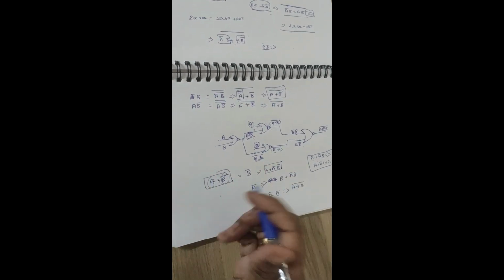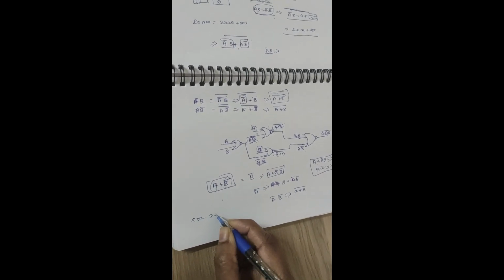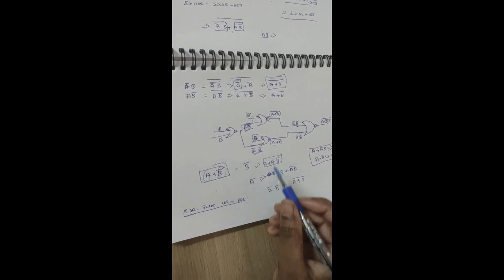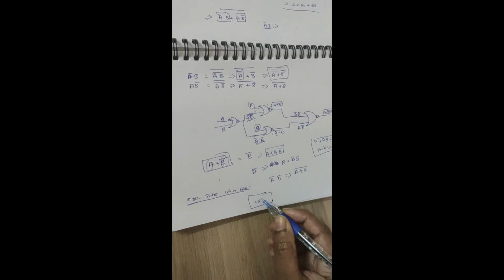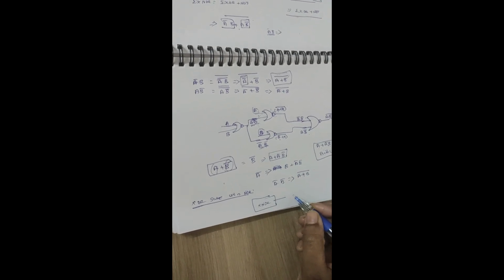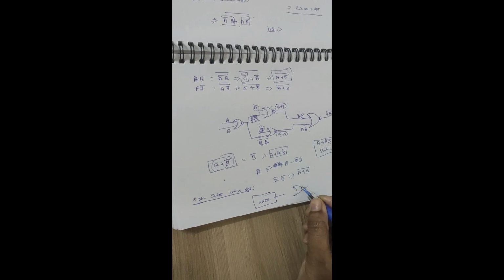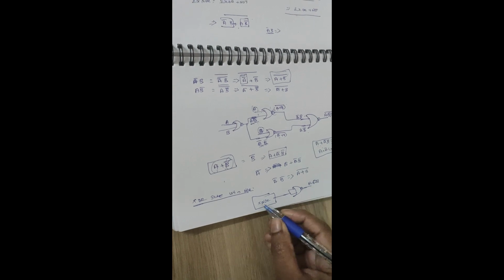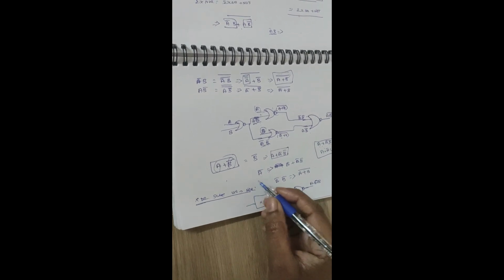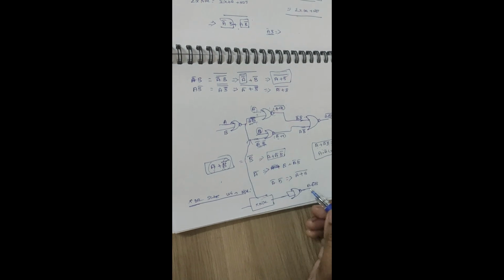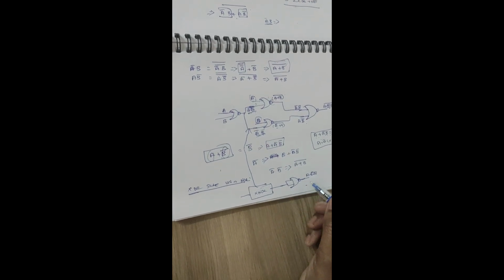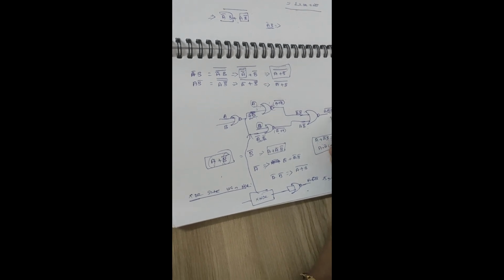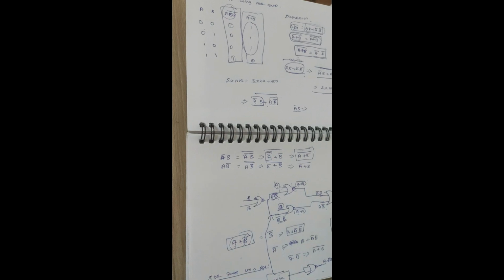Now if we want to implement the XOR gate using NOR, what we can do, same as this one, XNOR followed by one NOT gate. Here it will be A XOR B. This will be same as this one, and we can just add one NOT gate at the output. So 5 NOR gates will be needed for XOR, and 4 NOR gates will be needed for XNOR.